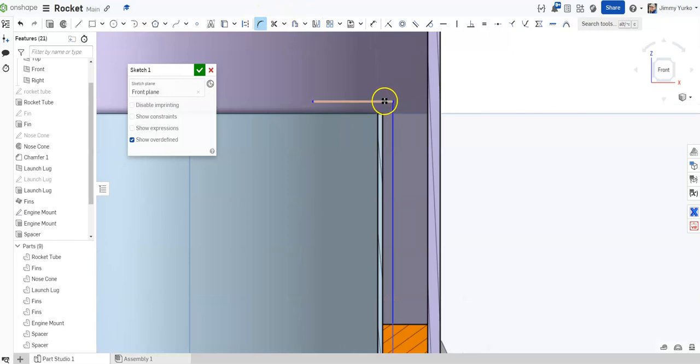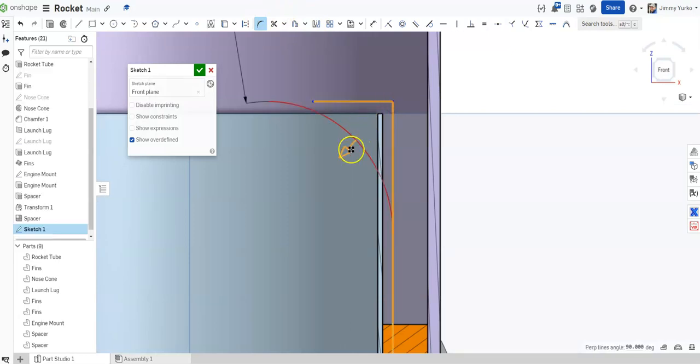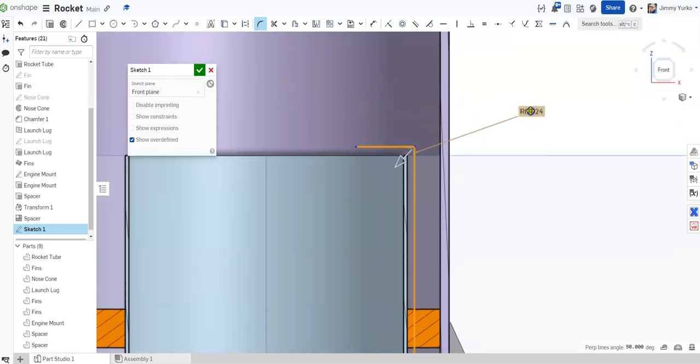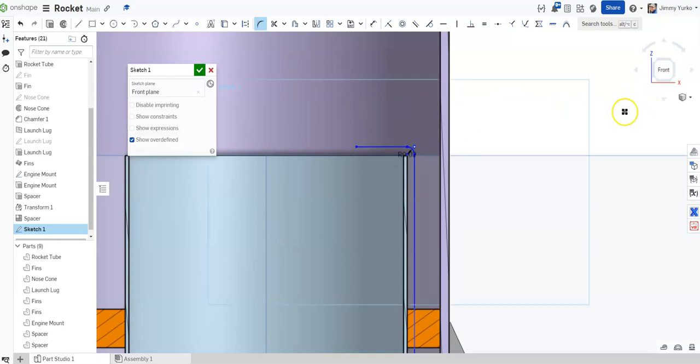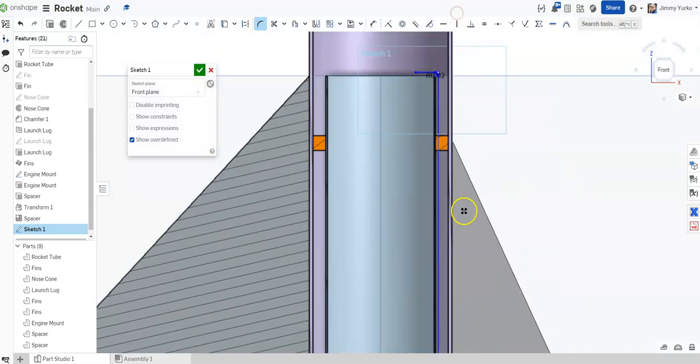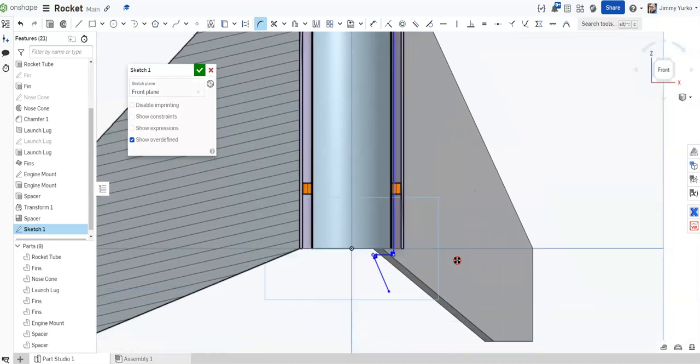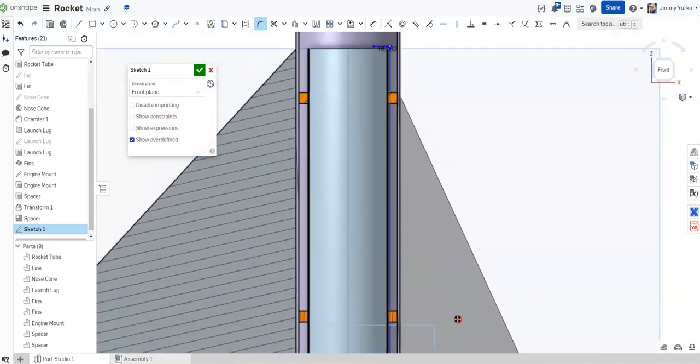All right. And we're going to fillet it because you can't bend a piece of metal with a perfectly sharp bend. So we need to get a fillet. Let's go with a distance, about 0.02 works for me. We'll use the same fillet size down here, and here. So we have that fillet. Excellent.